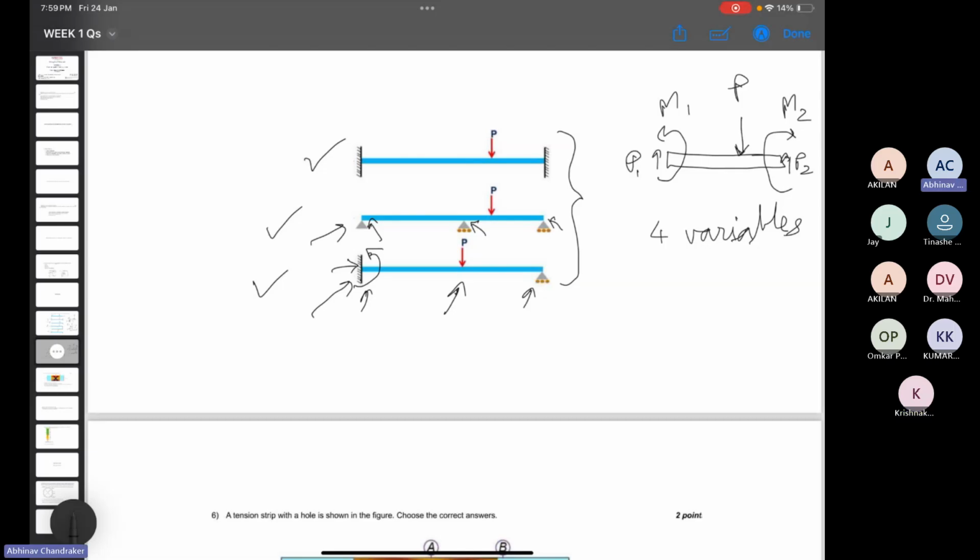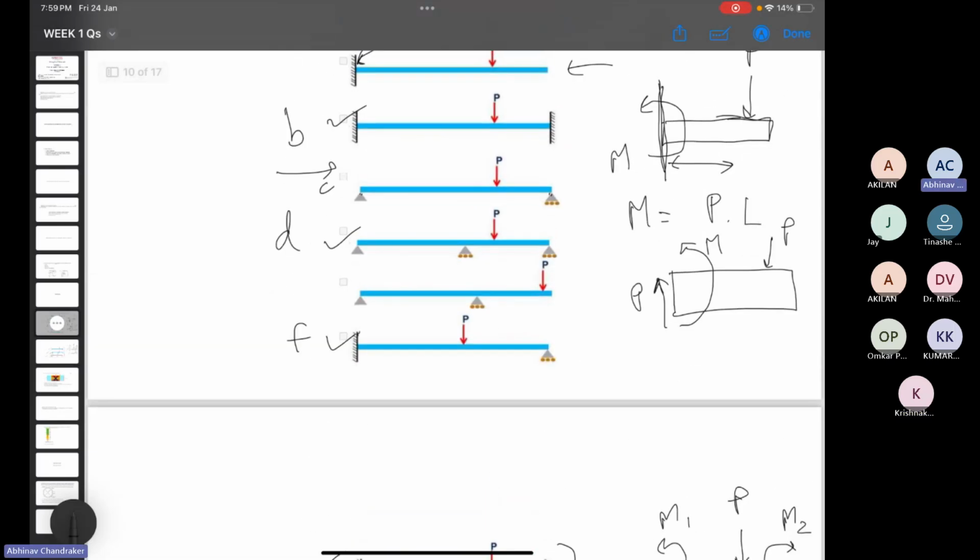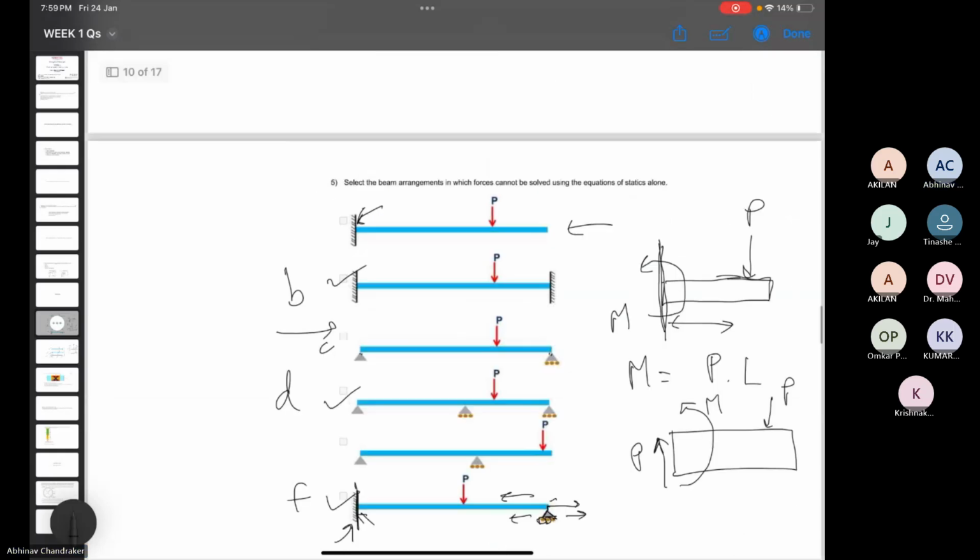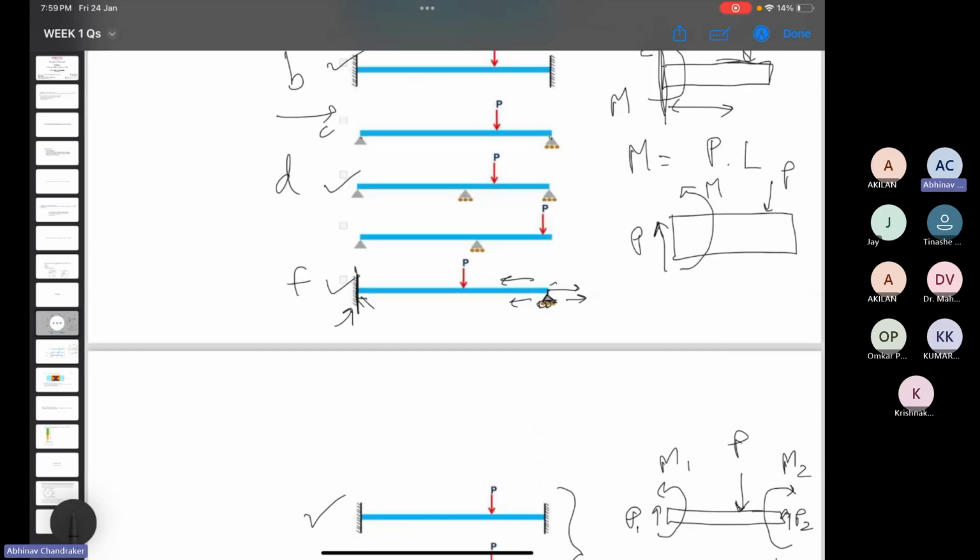Yes. So what this means is if you have this kind of arrangement, this is a wall, so one end of your bar is fixed at the wall, and the second end is in contact with this kind of thing. And here you have small bearings, so this can move in the x direction, but it can't move in the y direction. So the bar, this contact point with this portion can also move in the x direction. But here, since we are only applying force in the y direction, we are not concerned with this. So this is how the arrangement is. So it is only constrained in one direction. If you look at x, for y it is constrained in both directions. Sorry, not in both directions. At both points it's constrained for y, and for x it is only constrained at the wall, which is this one.